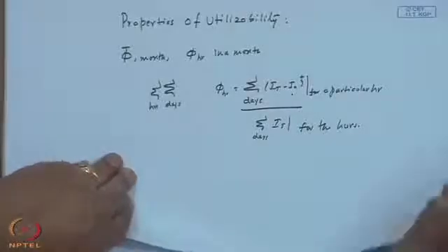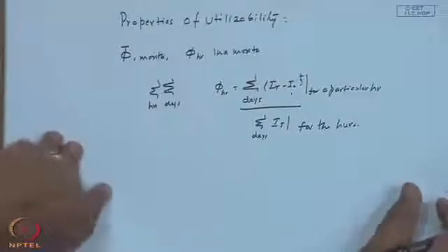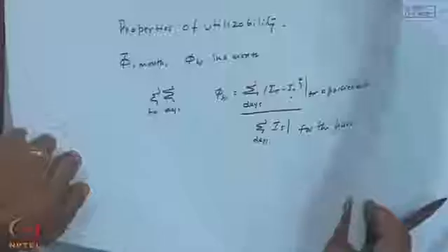This has got a bearing with my clearness index distributions, which we discussed a long time back, and again I will come back to that, because if the monthly average clearness index on a daily basis or hourly basis is 0.7, 0.6, whatever, there will be days with a clearness index less than that number, and there will be days with clearness index higher than that number.